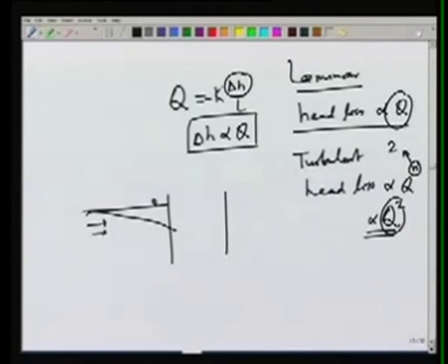So here the velocity may be small, but as we go near the well, the velocity becomes very large and the flow may not be laminar, it may become turbulent, and then there will be an additional loss because of this proportionality to Q square. Similarly, near a well we have a screen and there will be some head loss when the flow passes through the screen. So the total drawdown in the well will be a combination of these three terms: laminar loss, turbulent loss, and the well screen loss. So we will look at how to combine these to obtain the total well loss, which will define some kind of efficiency of the well.